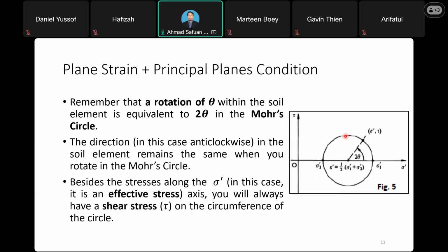Drained shearing essentially means that during the soil shearing, the water is drained out of the soil. So that is for the effective stress approach, which is usually defined as long-term stability.